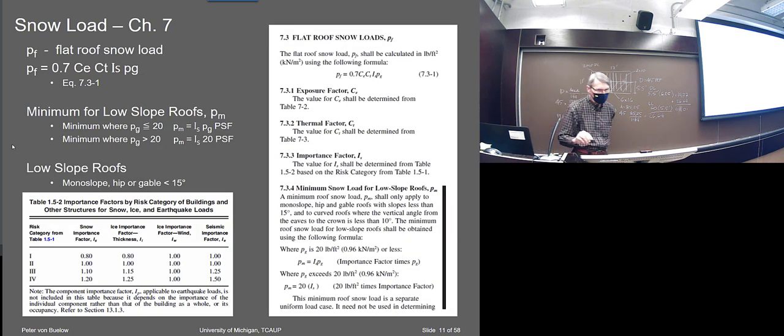So for the flat roof snow load, initially there's a 30% reduction on the ground snow, and this is the idea that you're elevated, some of it's going to blow off, and it probably won't blow back up on it, right? So once it blows off, you've lost it. So you'll lose maybe 30% is what the estimate is there, just from it blowing off.